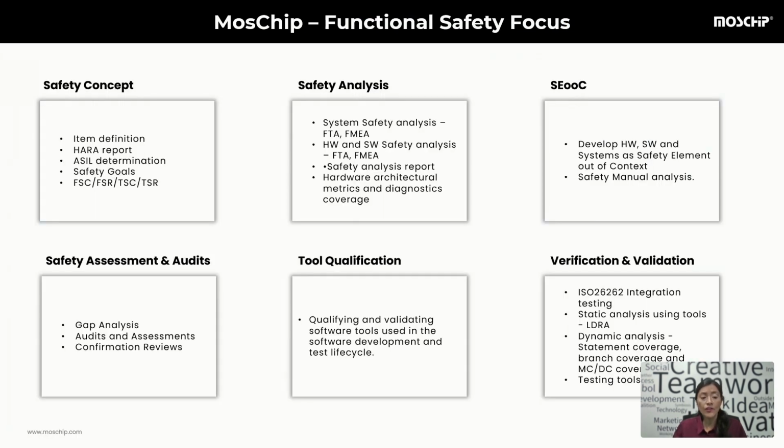If we talk about our functional safety offerings, it spans the entire ISO 26262 life cycle with a structured approach to both design time and runtime assurance. We begin with safety concepts, defining the item, running HARA, assigning SLs, and formulating safety goals and requirements across functional safety concepts, functional safety requirements, and technical safety requirements.